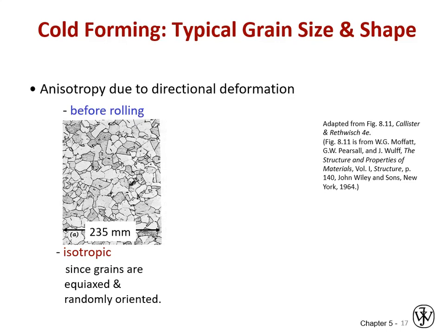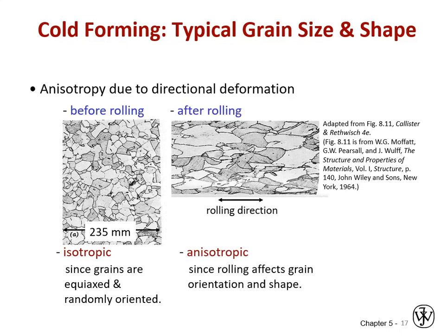And in our starting material, those are oriented equally in just about every direction. Well, say we applied some shear stress and we deformed it and we moved those dislocations. They moved first on all of the close packed planes and in the close packed directions of all the crystals that were conveniently lined up relative to the stress that we applied.